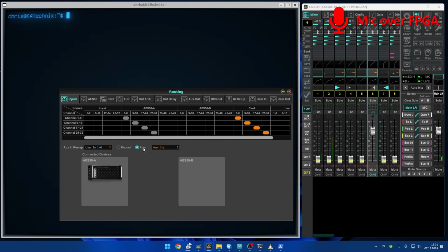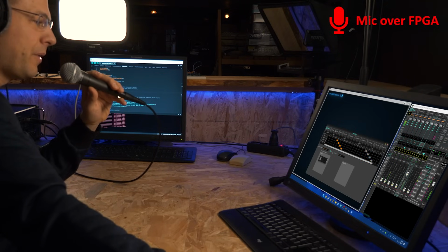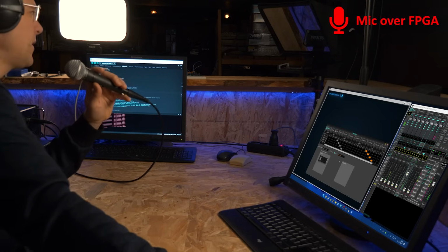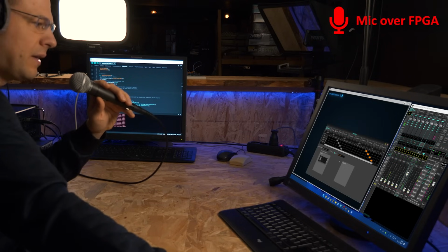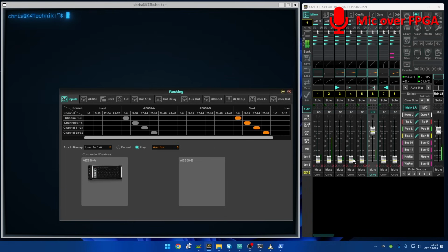Okay, yeah. I think it's working. I hear a bit more hiss and it is a bit louder. This is record, this is play. So there's something wrong with the gain, but I did not program any gain. So maybe I have a problem with some bit shifting here. I'm not detecting it. You can see here, there is noise increasing between channel 4, 3, okay, 2 is our sine wave, and 1, there's some hiss here. So this is the background noise, and I think I made a mistake here in placing the bits in the right position. But let's see if we can get the sine wave.